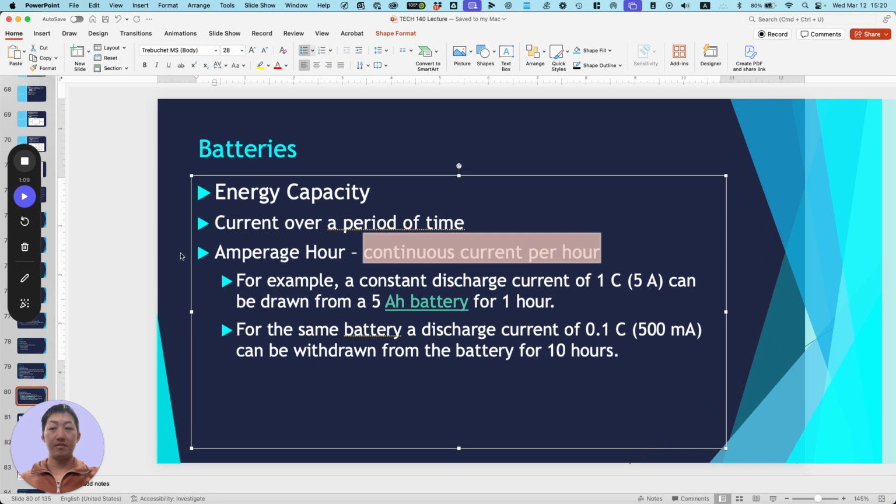Is the XT always the balancing plug, or no? No, we're talking about the main power plug. The balancing plug is a JST, the JST XH right here. Sometimes you'll find a JST RCY, and I'm just talking about main plugs there. The only plug that's not a main plug but a balancing plug is right here, the JST XH.